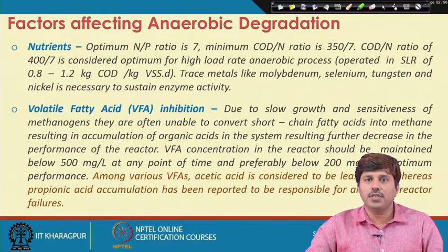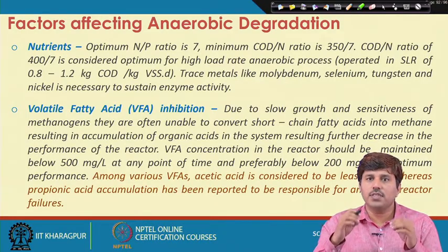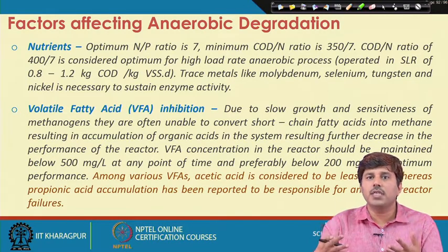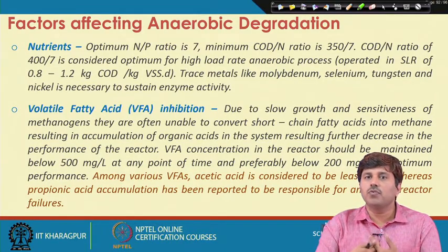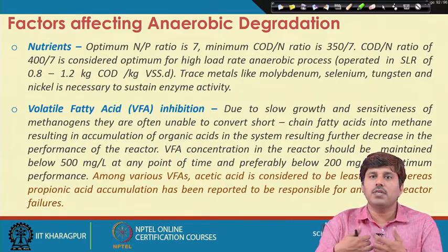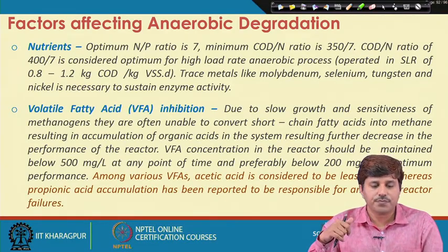A higher level of nutrients present in the system will not get removed because nutrient uptake is very low. There is some requirement of nutrients, which is fairly low as opposed to the aerobic system, but if more nutrients are present, it cannot take up all of them. So, the removal of nutrients will not be there, but the advantage is that because the requirement is low, if there is a need to add nutrients, we will have to add very little.